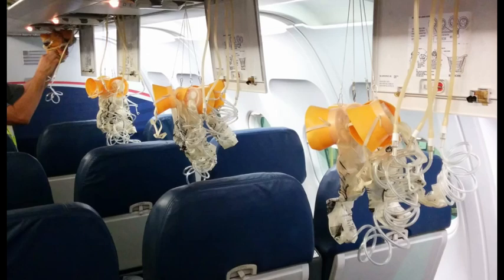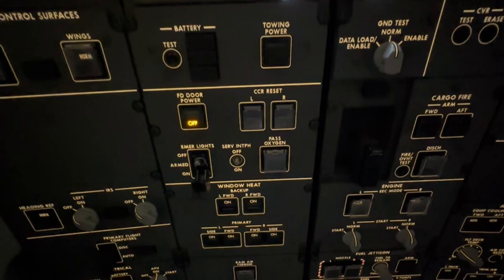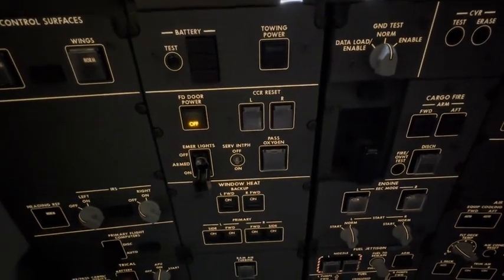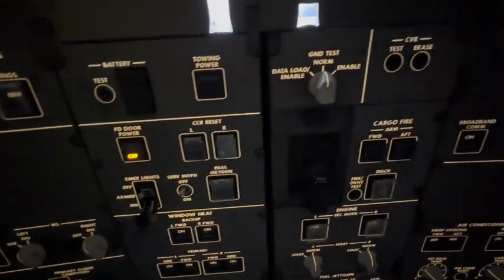Up next, we're going to take a look at the little switch right next to the passenger oxygen, which is the service interphone. It's simply an option to turn it off or on. But to the left of it is the more important one, emergency lights. On the ground, we will have it to off. When the toggle switch is down, it goes into the arm position. In case there was a loss of power within the cabin or aircraft systems, all the emergency lights will automatically come on. Or pilots can physically put it into on position. Maintenance can also do this for testing purposes.